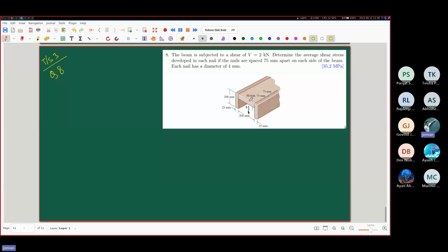Then this horizontal board is just the rest of the cross section with respect to those vertical boards. So if this is the entire cross section and you consider these vertical boards, then the horizontal board is the rest of the cross section, is it not? Then it must be true that if the Q corresponding to this one and this one is Q, then for the horizontal board it must be minus Q. By the fundamental point we had discussed on the previous page, that must be true. Agreed or not?